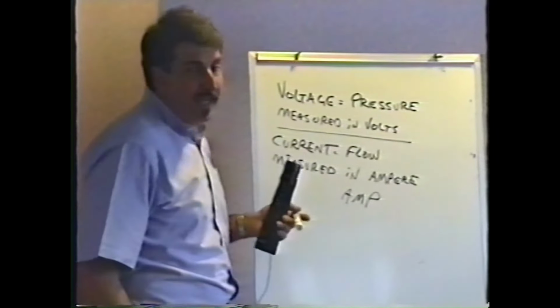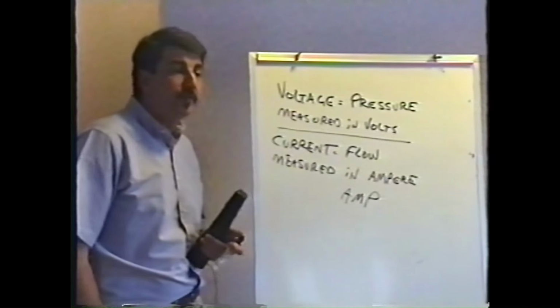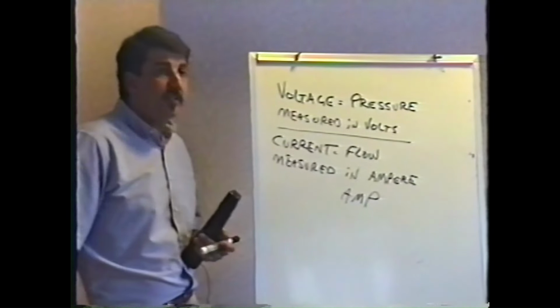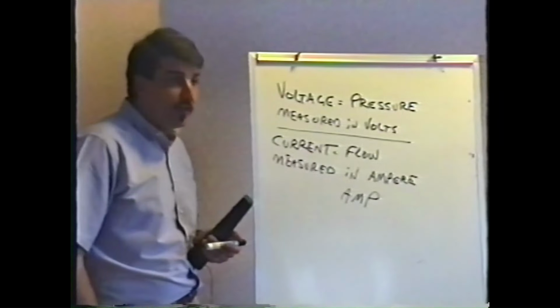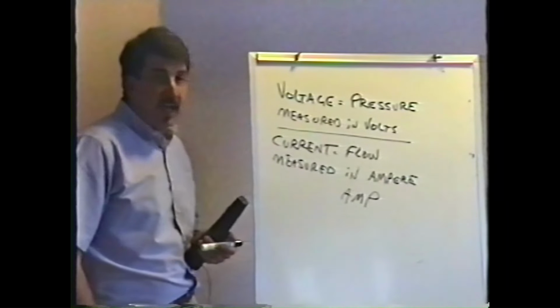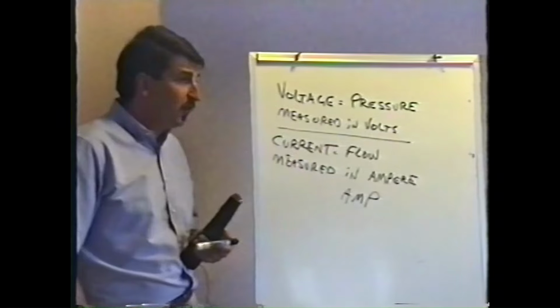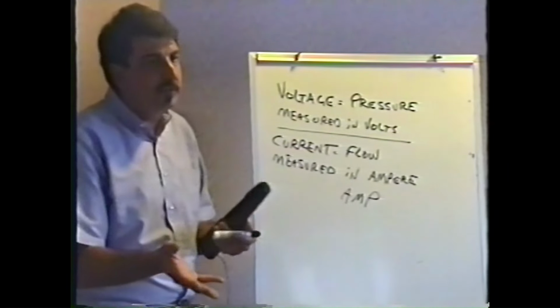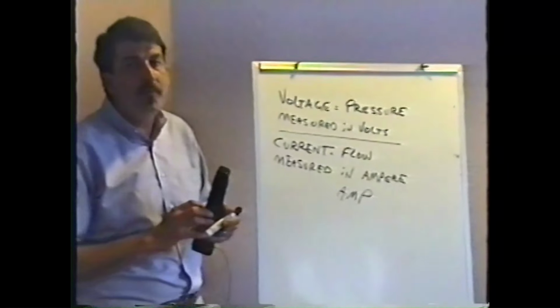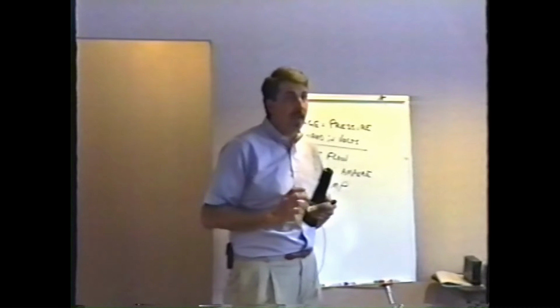Now, although the meter can measure amperes, we never actually measure amps. There's never any reason whatsoever, as far as a diagnostic tool is concerned, for us to ever measure current when we're working on games.